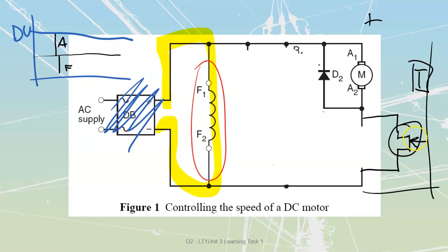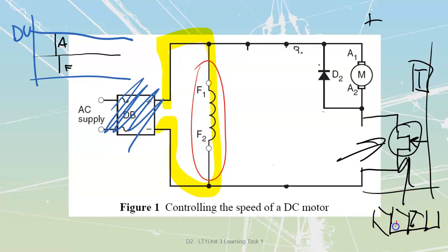That is then going to choose how much DC we're going to put through, and really these two get treated as being series voltage drops from one to the other. This would mean that my FET would be dropping a fairly large amount of voltage, as well as carrying a large amount of armature current through it. So you're going to have to have that thing seated onto a fairly large heat sink so that you can pull all of that heat off and dissipate it out to the surrounding air, right? We've talked about this before in electronics, how important that is.